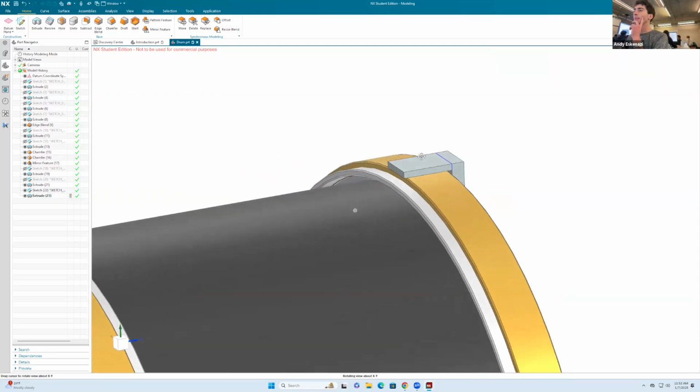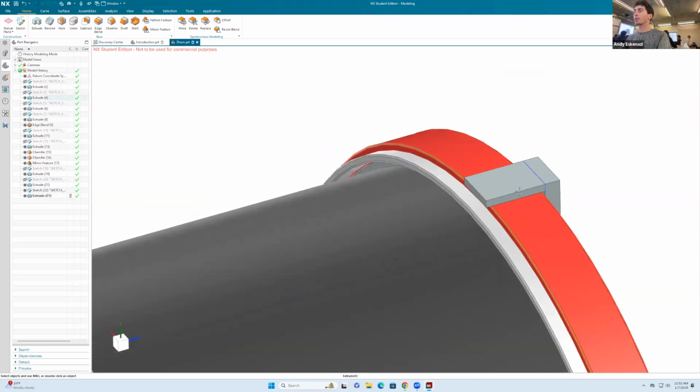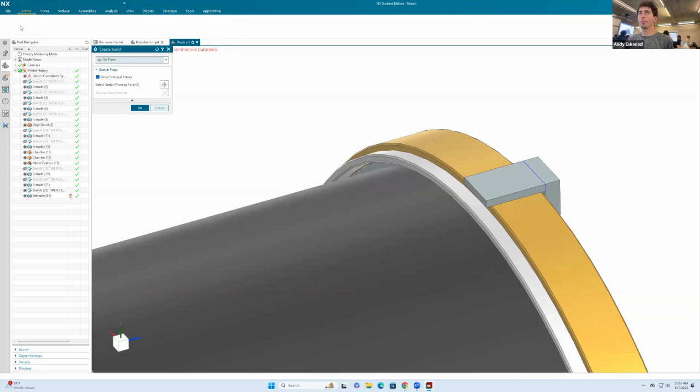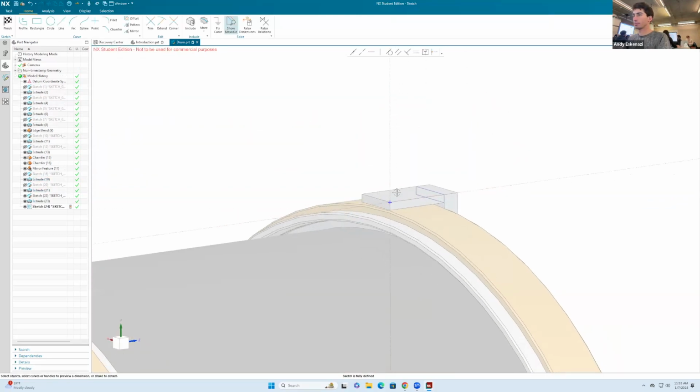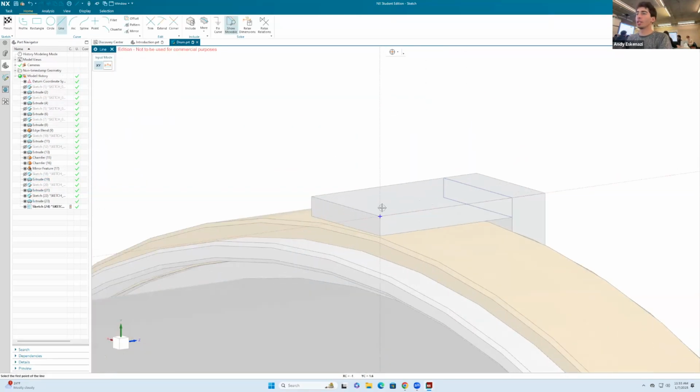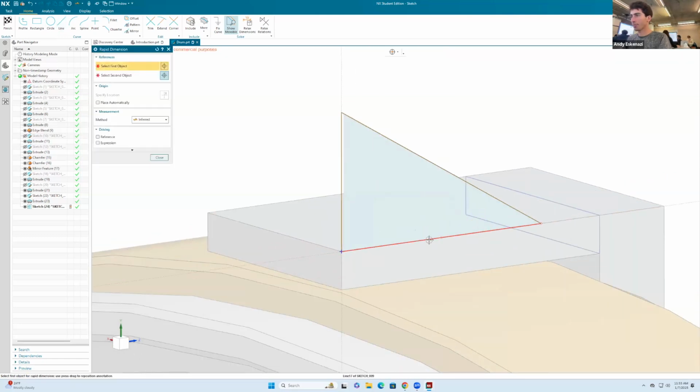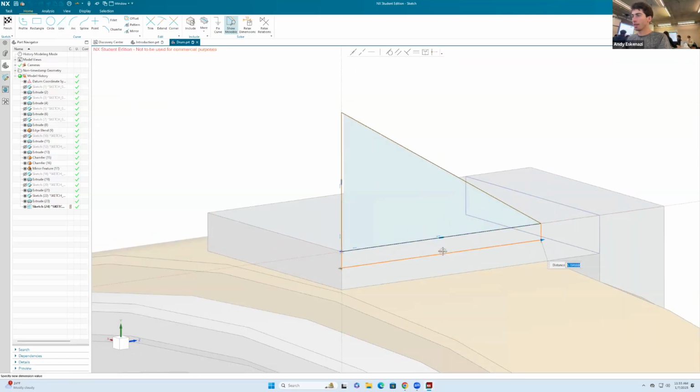I'm thinking now we're gonna get a little bit creative. We're gonna go here to sketch, and we'll do a sketch here on this face. Now I'm just gonna draw a triangle. Like this. And I'll make that maybe 5.